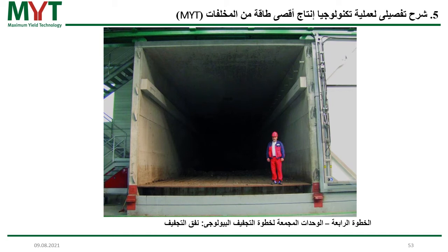You will always have dead zones where you do not get the oxygen towards. So by taking the material out and putting it into the tunnel again, we avoid the dead zones because everything is mixed and homogenized again. So this is how we can make sure that all waste in one tunnel is dried down to less than 10% moisture content.